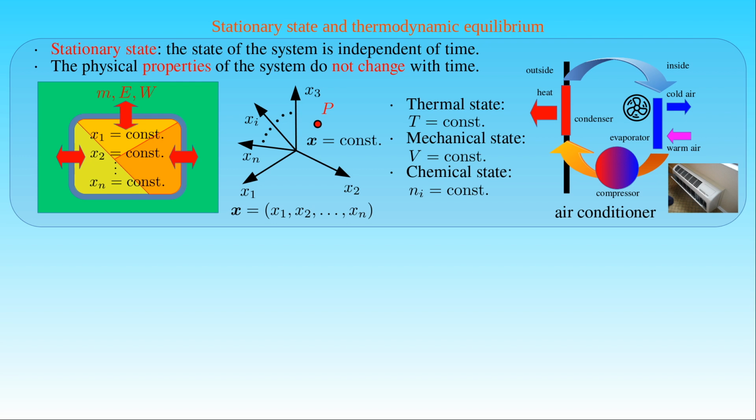The warm refrigerant is pumped outdoors to the condenser so that the heat can be released. The refrigerant leaves the evaporator in the form of a warm, low-pressure gas. In order to release the heat absorbed by the refrigerant, the gas needs to have higher temperature and pressure. The compressor reduces the volume of the gas to add pressure and increase temperature.